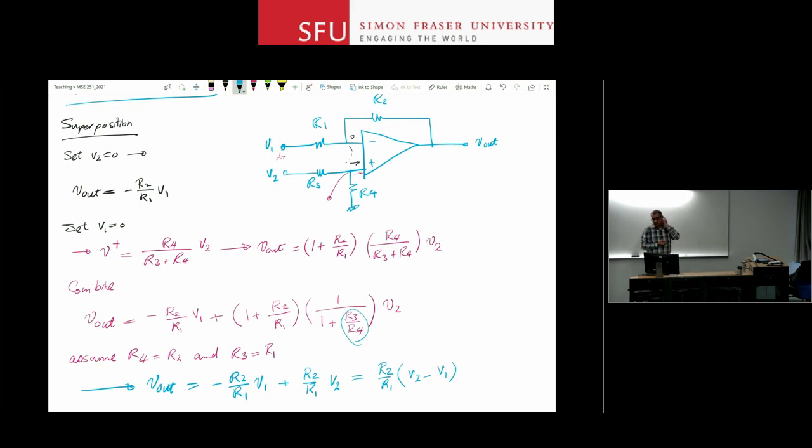Now, you can also divide signals. If I want to multiply by a constant gain less than 1, you can still do that. You can make a circuit to do that. But it is also possible to make circuits using OpAmps to do other types of mathematical functions on signals. So you can have a circuit that multiplies two signals by each other, or takes the logarithm of a signal and puts it at the output, or puts the exponential value proportional to the input signal at the output. You can do all sorts of those things with an OpAmp circuit.